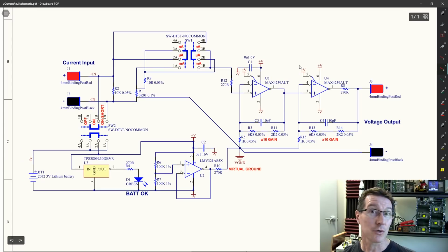Let's go. Just a quick design explanation why we need a low offset voltage here. In this particular case, in the order of 0.1 microvolts nominal, which is what the Max 4239 has. Well, that sounds like bugger all. What's wrong with even 100 microvolts or something like that? Well, the thing is, you've got a total gain of times 10 and times 100 gain here. So any input offset voltage, here's your input, if you have 0.1 microvolts typical offset voltage here, you multiply that by 100,